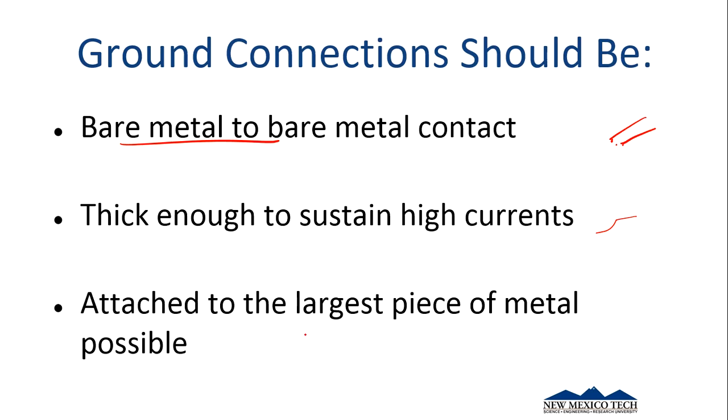And what I mean by that is that's the point of the chassis ground. If you have this big enclosure, it's really nice to be able to ground to that versus having your current flow to some smaller piece of metal and have this be at some potential voltage there. So that's all I really need to say about grounds.